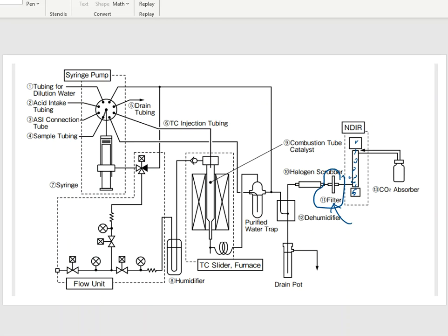All right, so if you're going to be doing maintenance on the inside of this thing, or if you have a routine maintenance schedule, this is not a pain. It's just a few screws that you've got to loosen up. You take the side cover off, you exchange the filter, and you put the side cover back on. No big deal after that.